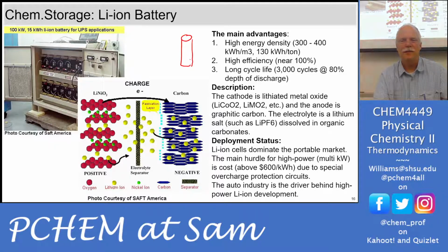And Thomas and I, for a while there, were pulling these out of laptops. Like you have a junker laptop, the battery's dead. Typically, it's one of those cells out of 15 cells that have gone bad. So you pull it out and you test all of the ones, and you get the other 10 that are still good, and you can make yourself a phone charger. The problem is trying to weld them together. To provide a 10-hour phone charger, you've got to weld these leads together and put them in parallel with each other.